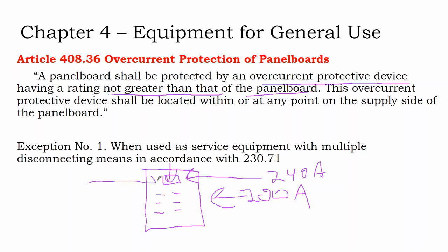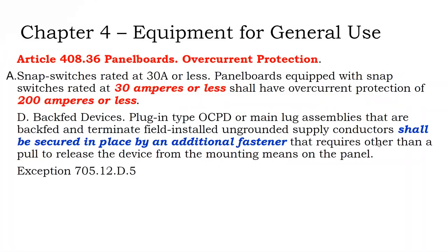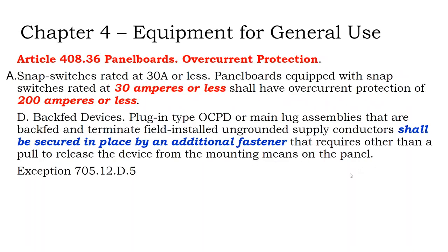Sometimes you'll get a 225 amp main breaker on a 200 amp panel, but if you go and look at the inside of it, they've actually given that bus bar rating a 225 amp rating. It's an unusual circumstance. And so they say, okay, there might be some different circumstances. We'll talk about that in the interconnection discussion in a little bit.